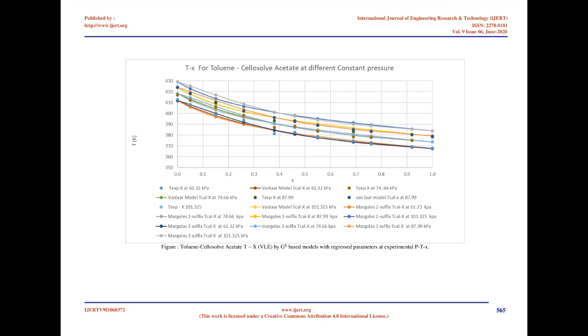5. Conclusion. The experimental work in this project involved generating pure component and binary VLE data for Cellosolve acetate, 2-ethoxyethyl acetate, toluene. The purpose of taking up this work was that 2-ethoxyethyl acetate is synthesized by the esterification of 2-ethoxyethanol and acetic acid using reactive distillation. To increase the yield of the product and minimize energy consumption, toluene is added as an entrainer. This makes the knowledge of VLE of the species along with toluene also necessary.